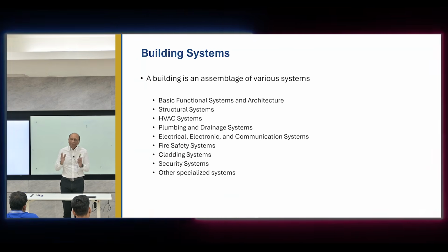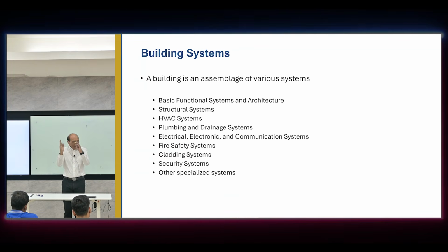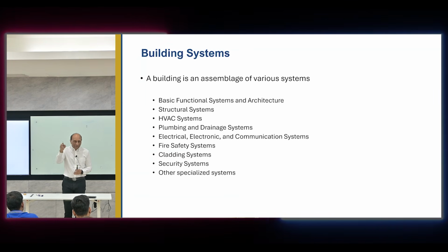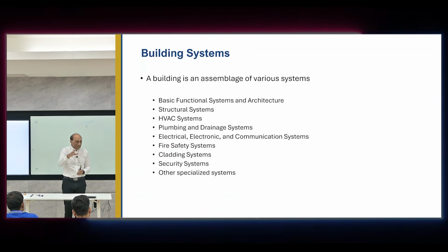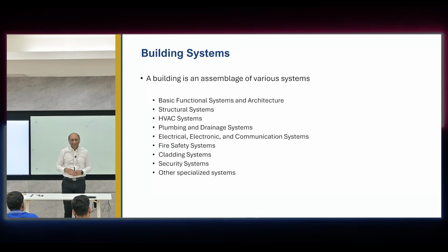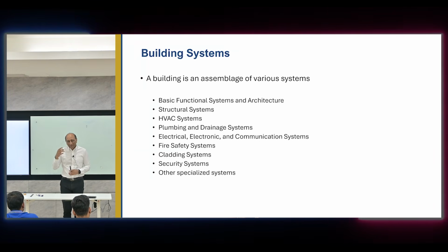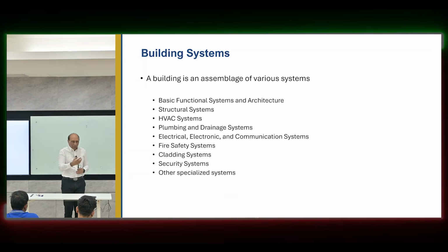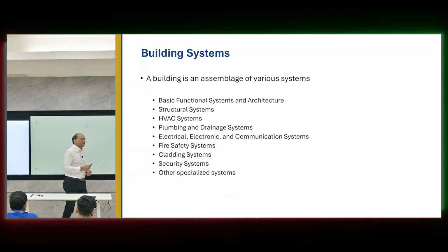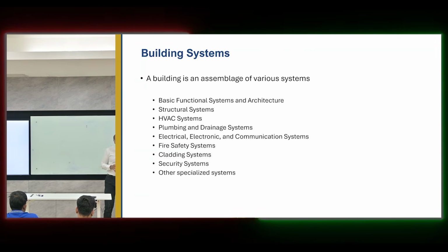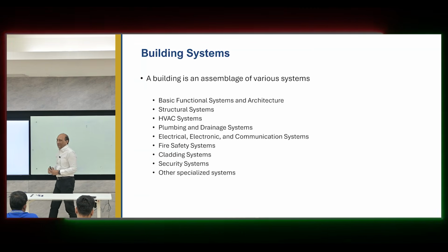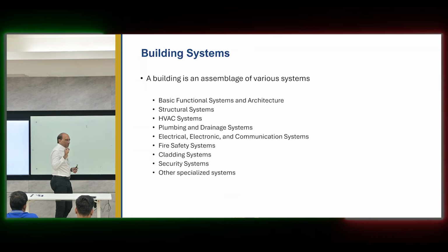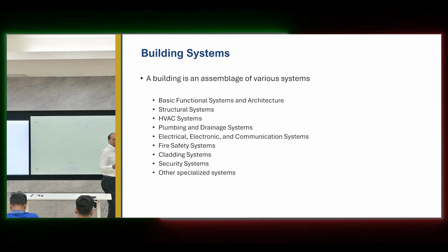So if the building is moving that much, the cladding has to be designed to adjust to that movement without breaking, without having cracks, without falling down, without letting in water. And look at the wind that will blow on it at that height. Look at the hurricanes, the water, the rain, the snow, right? So cladding is extremely important and needs to be designed as a major part of the tall building because it must accommodate the huge movement, it must accommodate huge weather changes, and must protect the people.